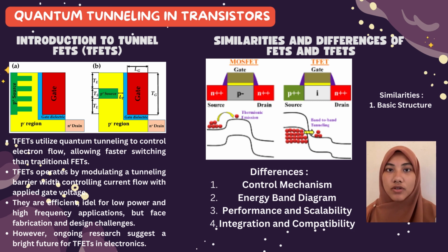TFETs operate based on the principle of quantum tunneling, which allows electrons to pass through barriers that would otherwise block their movement under classical physics. TFETs use a PIN or NIP structure where the middle part, I, has an equal number of electrons and holes, making it highly resistive. By applying a voltage to the gate, it can adjust the energy levels to open a tunneling window, allowing electrons to tunnel from the source to the drain.